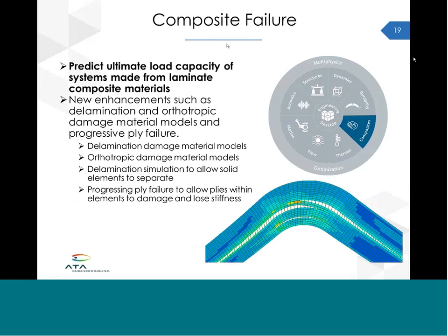Now, one of the other new capabilities that have been introduced to Simcenter 11 is significant support for analysis of composites, and particularly for analyzing the failure of composites. Those of you who have some experience with composites will know that they are quite a bit different than traditional metallic structures in that they don't exhibit a very large degree of ductility. Their failures are often brittle, they're often sudden, and they're often characterized by multiple failure modes. You might have in-plane failure modes where the fibers of the matrix split. You might also have inter-ply failure modes or delamination where the plies separate from one another.